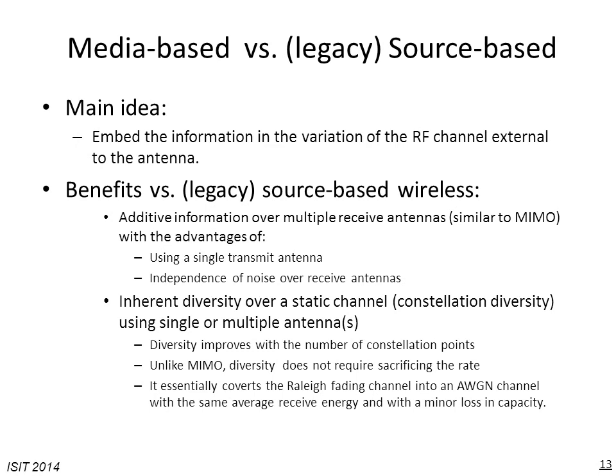Constellation points may have a low energy, which corresponds to channel conditions of low gain, or may have a high energy, corresponding to the channel configuration of a higher gain. But of course, in any multi-level, multiple-point constellation, we always have points that are closer to the origin and points that are further away. So having channel conditions that have low gain and contribute to the points close to the origin is not really a bad phenomenon, at least not as bad as it was in the case of a source-based modulation with a static channel.